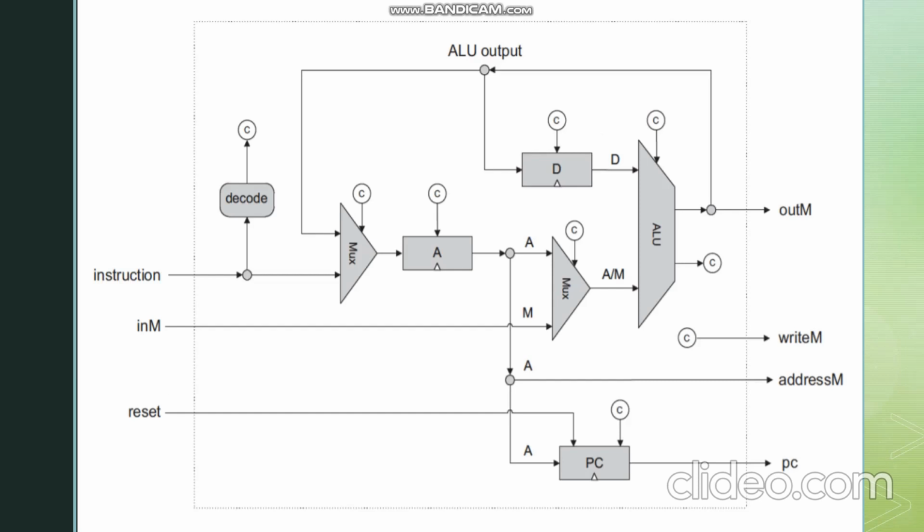In order to do so, the CPU must specify a few things. Firstly, the content that the CPU is going to write in the data memory, which is stored in the outM. Second, the address of the write operation in the data memory. Basically, this is where we want to put the content in the data memory. Lastly, the output that allows the CPU to write the content to the data memory: writeM.